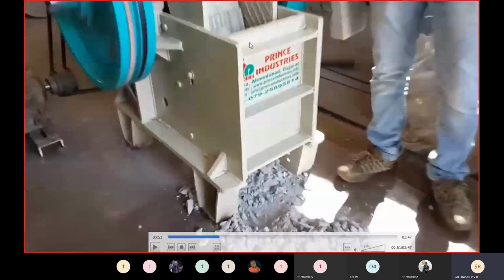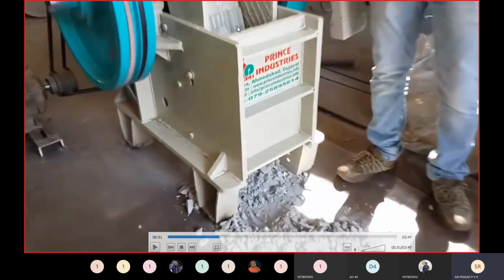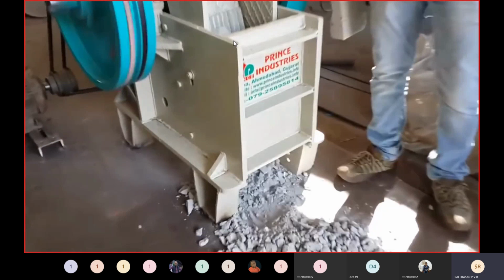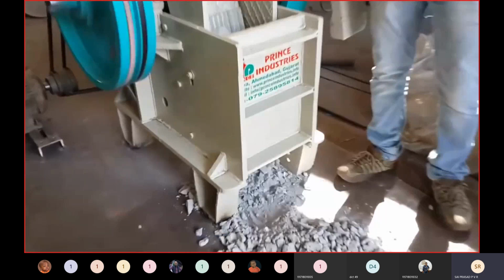See, we are giving some time, that is important. In the industry, they may not give importance to power consumption, but once we charge the material, we are supposed to wait till the entire crushing takes place. As the particles come out, which is visible to us, we can see how the crushing is taking place. Once the solid has fallen down from between the V shape and no solid is there, then we can add the second solid particle, and thus the crushing takes place.